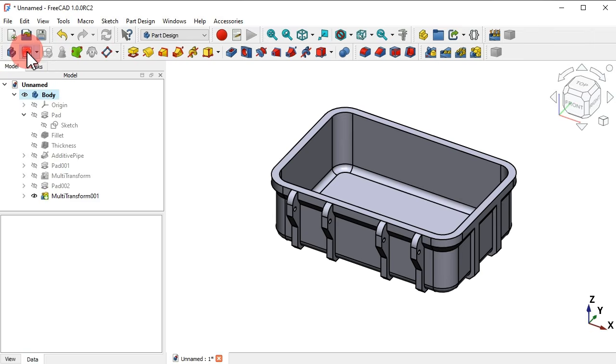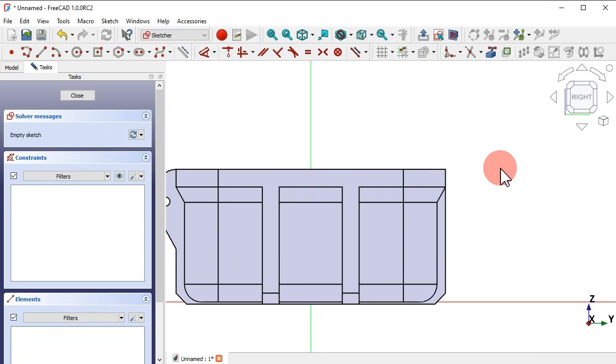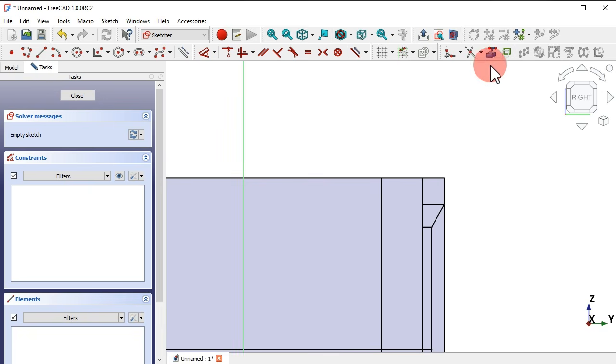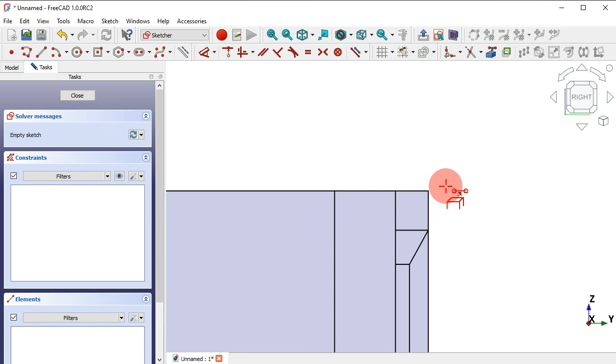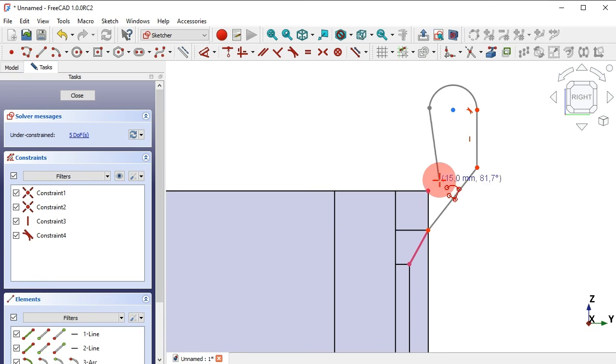Next, let's create a new sketch on the YZ plane. Just zoom in and switch to the section view, and now select the external geometry tool, extract this point here and also this line, and next select the polyline tool, and the first thing to do is to create this line in this way, and next this vertical line, and now just press M 3 times to create this arc here, and now 2 times to draw a simple line, and just click on this point.